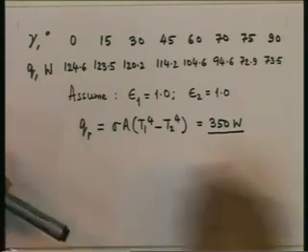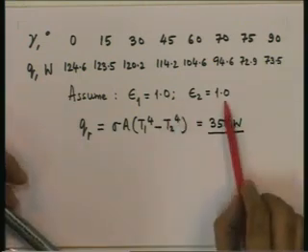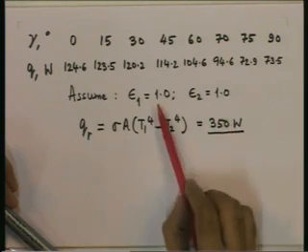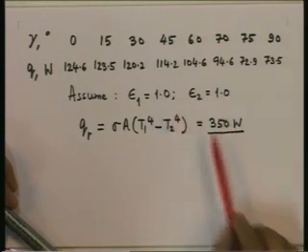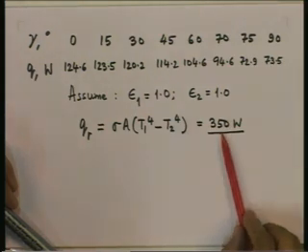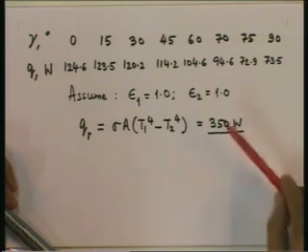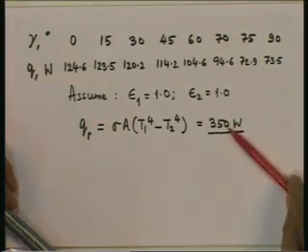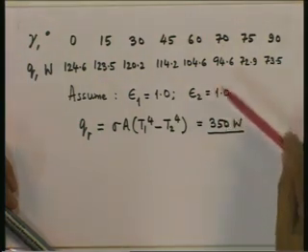Even if the emissivities were slightly lower, for example, if this is 0.5, even then this is 175 watt. And that means in this situation, whatever be the inclination, the radiation is going to dominate the natural convection.